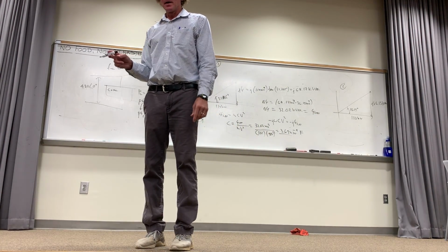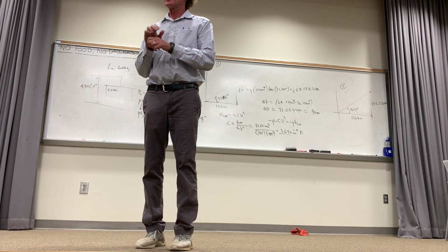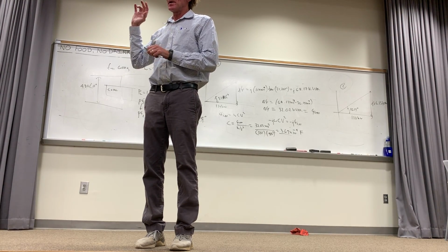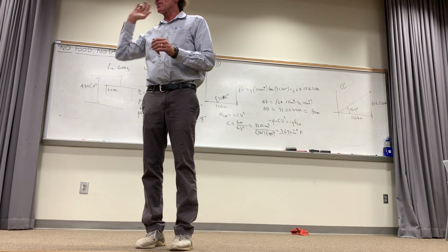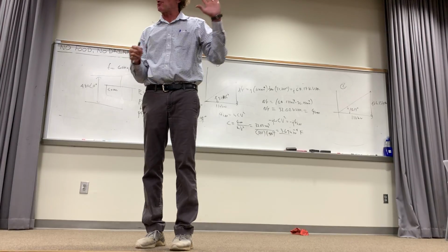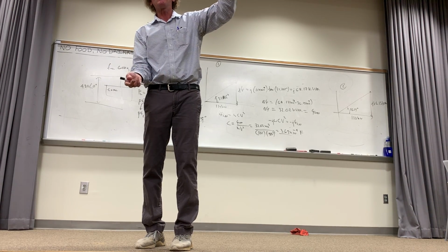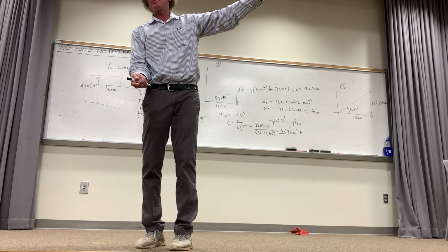Okay? That's it. That's what happens when you want to reduce the actual complex power in a system. And that's what industries do. West Point Petrol would do it, General Electric would do it, any large consumer of power would do this. They basically have banks of capacitors, large amounts of capacitors, that they start putting more and more in parallel to get the correct power factor. Now the power company will fine them if their power factor is above a certain amount. And that's why they do it.